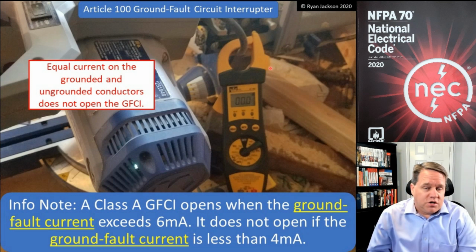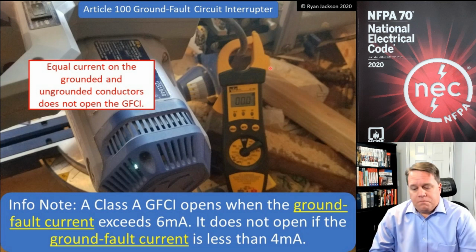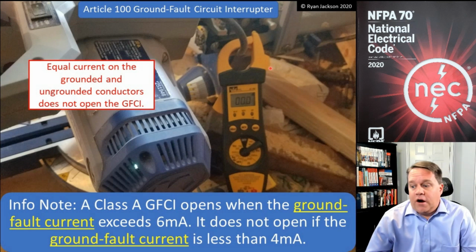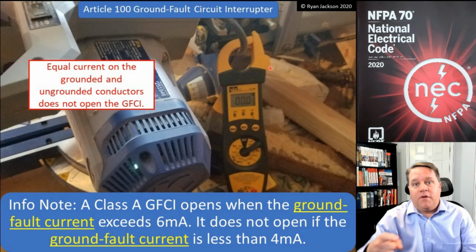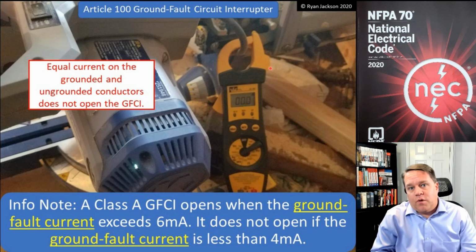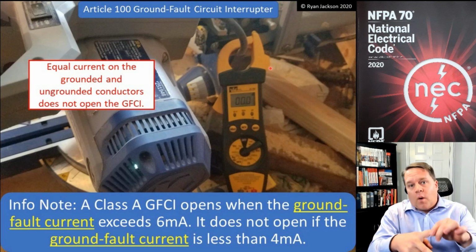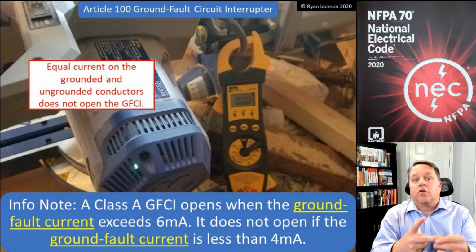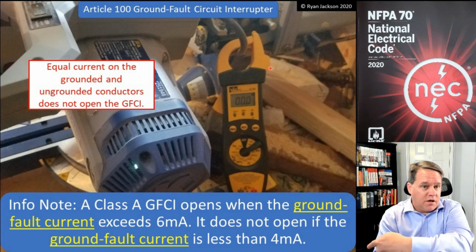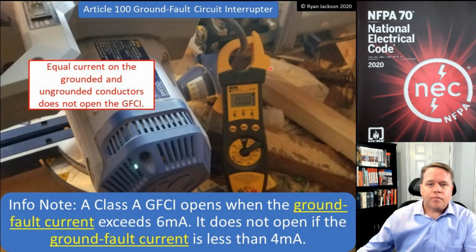So if I had an air conditioner that I needed to GFCI protect, for example, do I have to have a neutral? No. I can just take my two conductors, and if the air conditioner pulls 23 amps, that means 23 amps on the black, 23 amps on the red. The GFCI measures between those. It equals zero under normal conditions, so it doesn't open. If one of those two conductors started pulling more current than the other, well then that means that current's return path is going somewhere unintended, and it's going to open the GFCI.